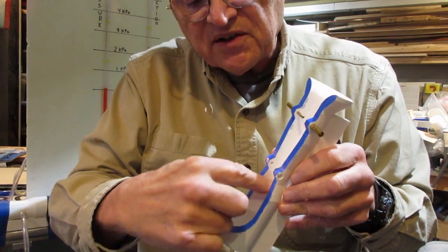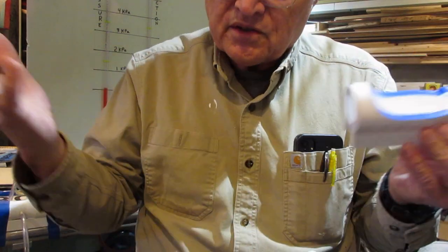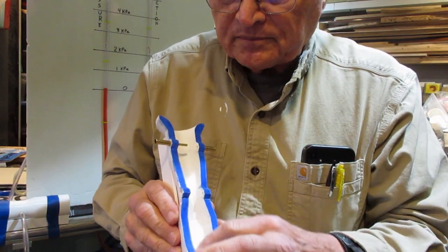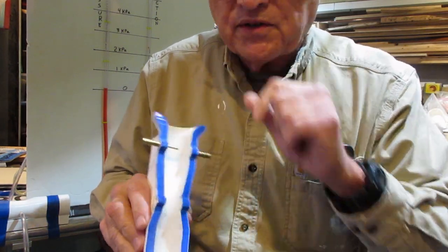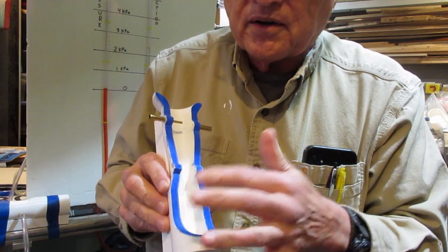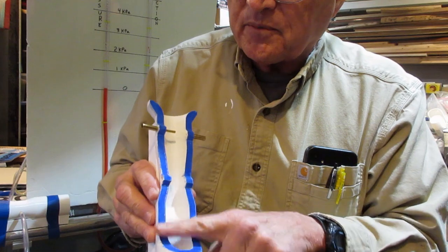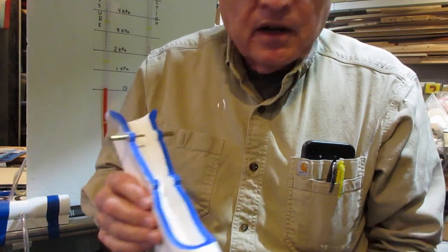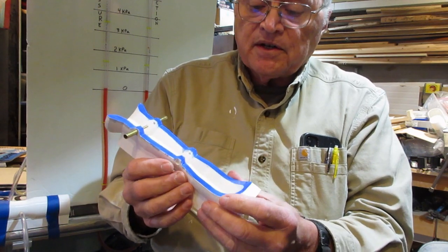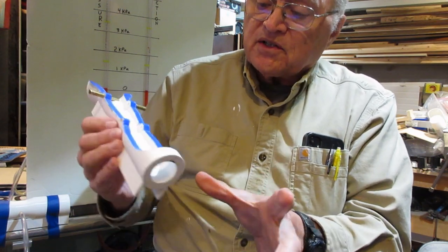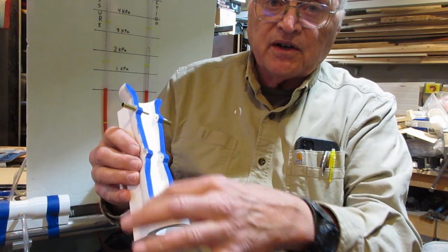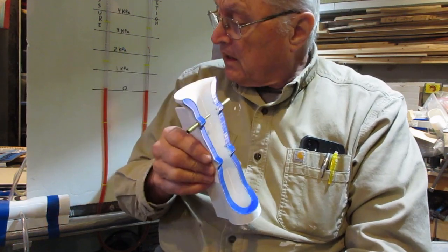So once you get past here, the pressure recovery, how much of the original pressure you get back, is really bad, and your measurements fall apart, and forget about Bernoulli from there down, okay? Of course, that would be another thing you could do, is maybe make a 2-piece Venturi, so you can make it taller and make this more of a gradual thing, and you could measure pressures on the way in and the way out, okay?